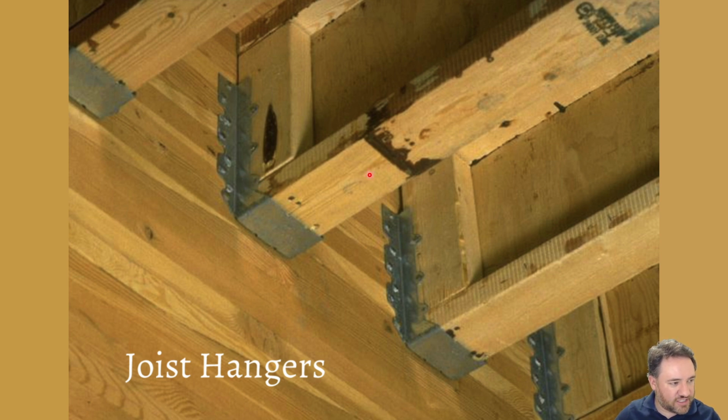Another interesting thing is here, this is a wood I-joist, and you remember that for joists and beams we're required to provide rotational restraint at the support, top and bottom. We're supposed to provide lateral strength top and bottom at the end of a beam, right? That was one of our requirements when we did beam design.